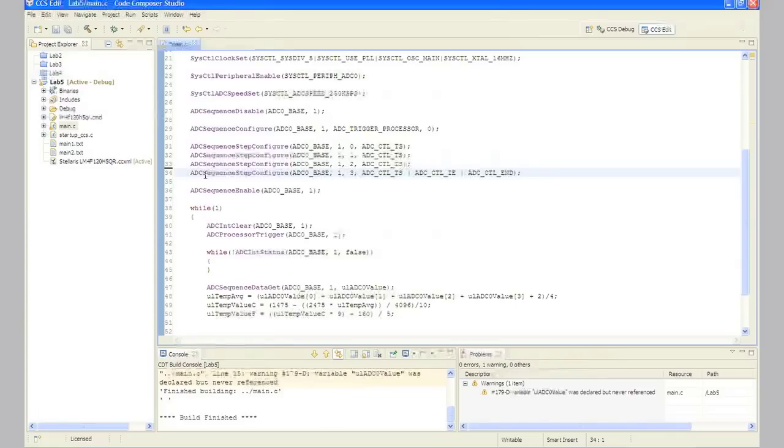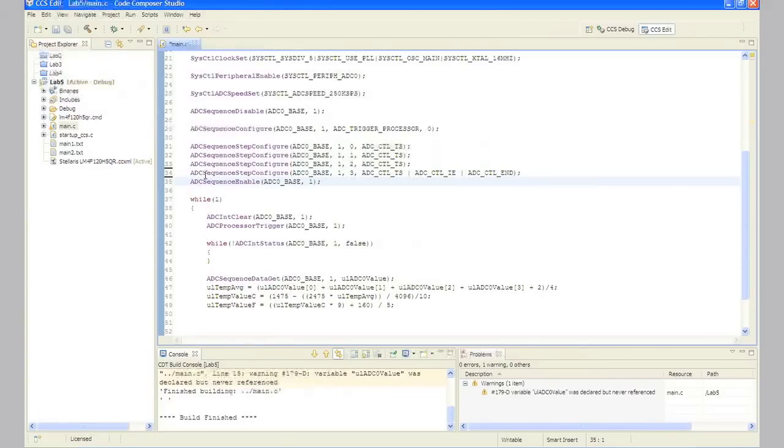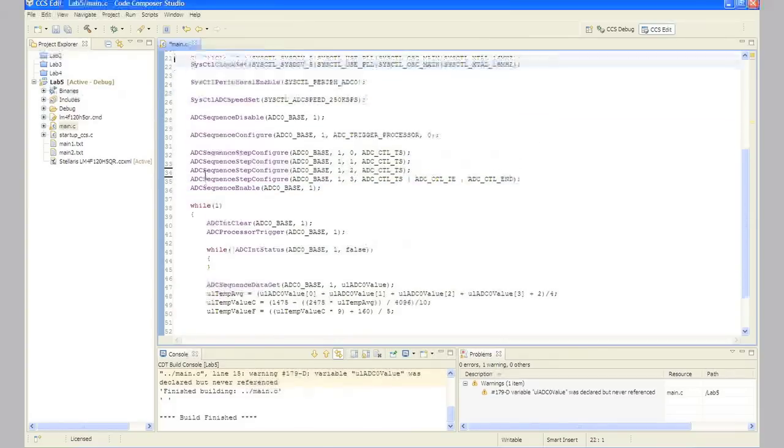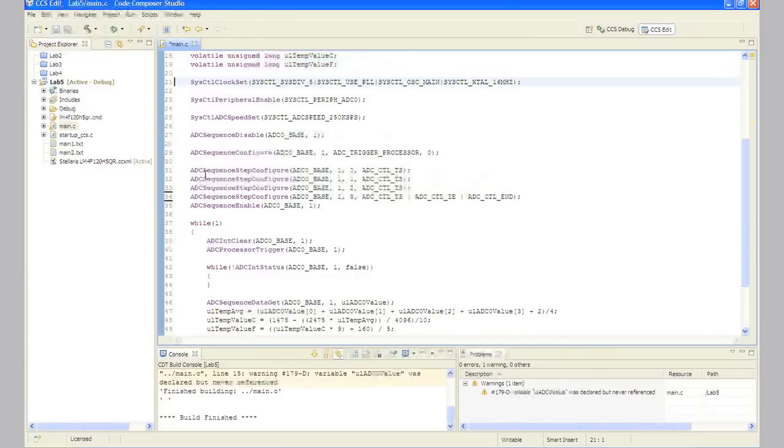So back at the beginning, we had the error checking on our APIs, but we have not added a DEBUG predefined symbol. Let's go ahead and see how that's done. In step 25, right-click on Lab 5 in the Project Explorer pane and click Properties.